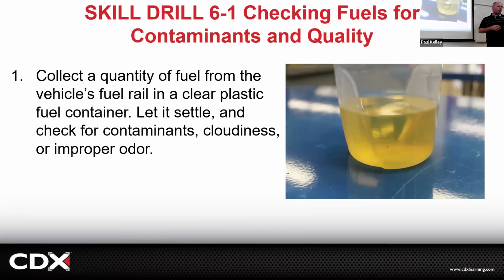Then as we go to do that fuel sample, this is what I did. I collected the sample, and you can see that looks kind of amber. I mean, that could be normal, but sometimes when gas gets older, it gets oxidized, and it does tend to change a little more yellowy. That one to me is a little sketchy. That one's like a little, I don't know.